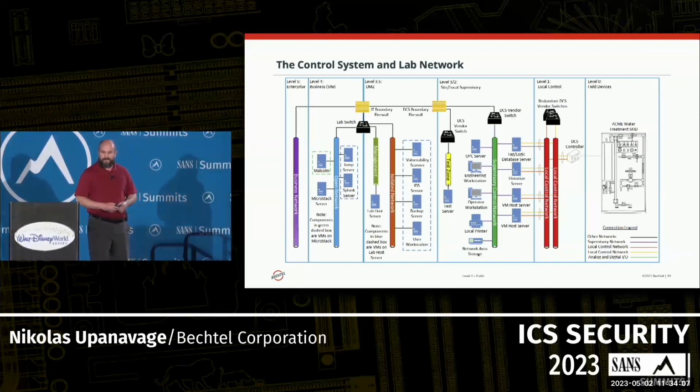That feeds into a DCS controller at our level 1. This is where the control logic is pushed, and it's taking all of the analog and digital signals from the instrumentation on the skid and performing the actions that we program on the system. Because we're in one small location, we combine our levels 3 and 2 into a site local supervisory network.